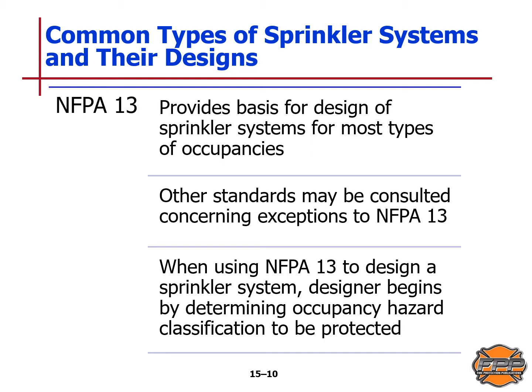NFPA 13 provides for the design of most sprinkler systems for most types of occupancies. Other standards may be consulted concerning exceptions to NFPA 13. When using NFPA 13 to design a sprinkler system, a designer begins by determining the occupancy hazard classification to be protected.